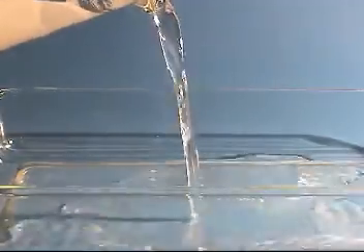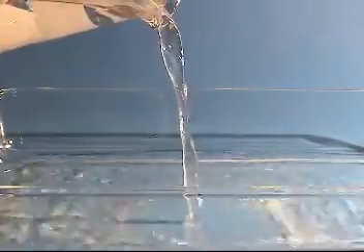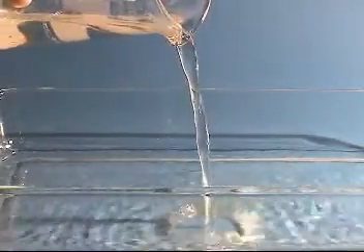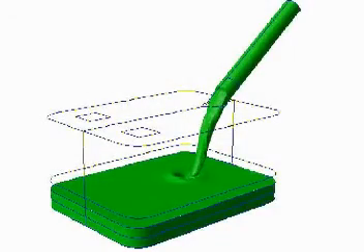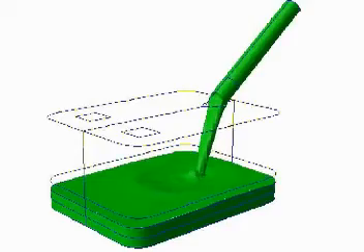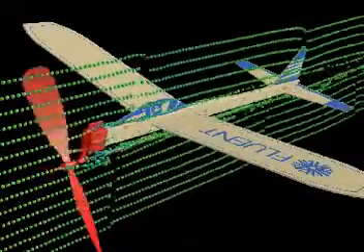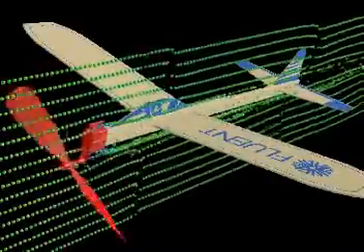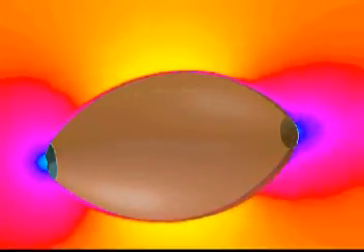Next, we classify flows as incompressible or compressible. Most liquid flows are incompressible. Thus, we keep the fluid density constant when we solve the equations of motion. Gas flows are also incompressible at speeds much less than the speed of sound, as in the airflow around a toy airplane or around a spinning football.